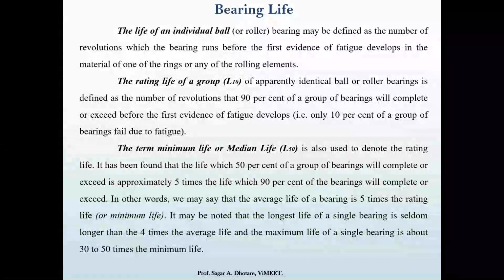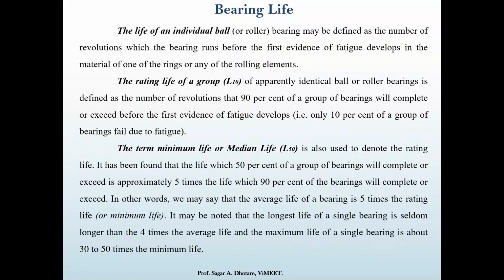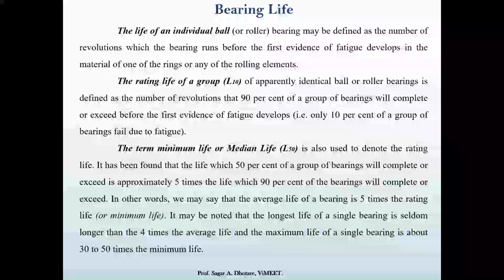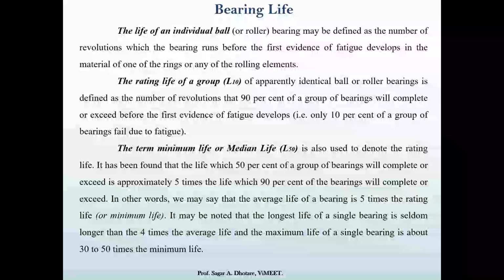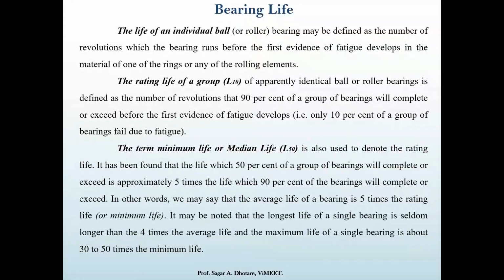Now in case of 90%, or you can say the L10 condition, or the rating life of a group, in the same condition, if I choose a lot of 100 bearings, then out of that, 90 bearings can perform very well.